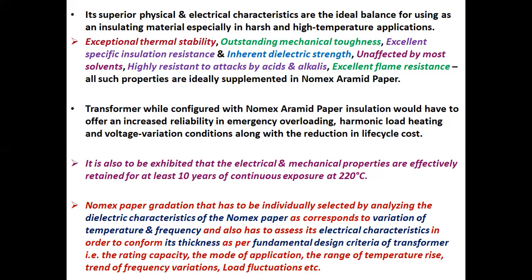So, Nomex paper gradation has to be individually selected by analyzing the dielectric characteristics of the Nomex paper as corresponds to variation of temperature and frequency, and also has to assess its electrical characteristics in order to confirm its thickness as per fundamental design criteria of the transformer, that is the rating capacity, the mode of application, the large range of temperature rise, trend of frequency variations, load fluctuations, etc.